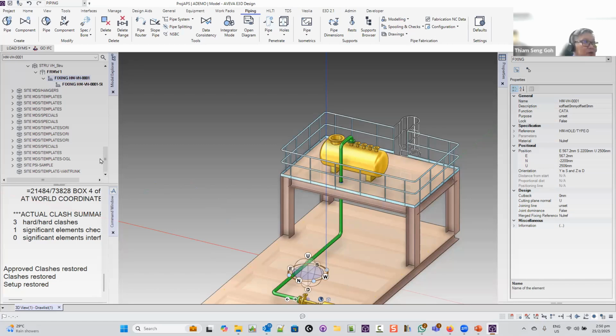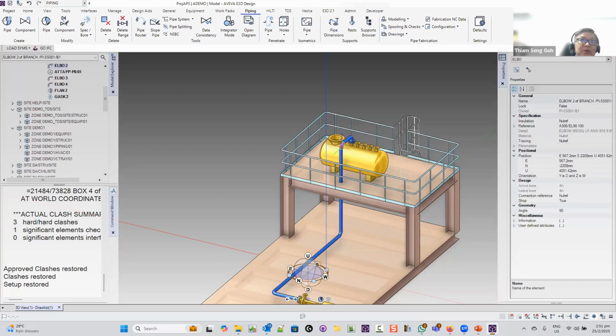But you have to put in the actual volume. All right. How to model a mitre fitting? A mitre fitting can be set up in the catalog with a special attribute for the bend to tell you whether it's 3D, 2D, or 4D, or whatever information you need, so that it will be modeled as a mitre rather than a curve. So it uses a bend. Just now when we wrote, these are elbows, these are not bends. So if you want to use a mitre, you use a bend to do that.